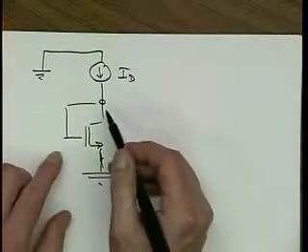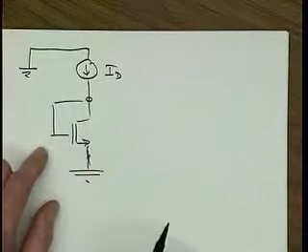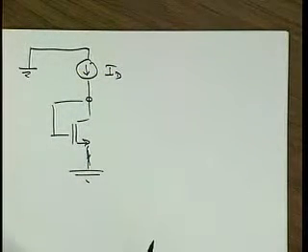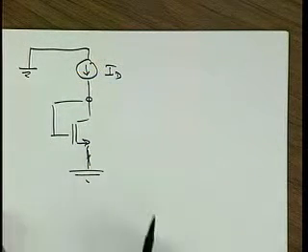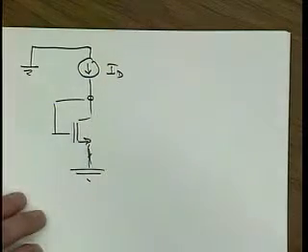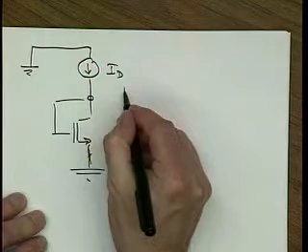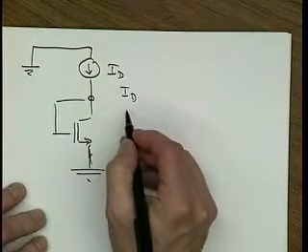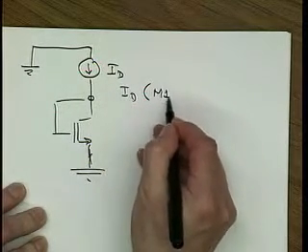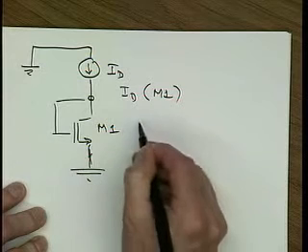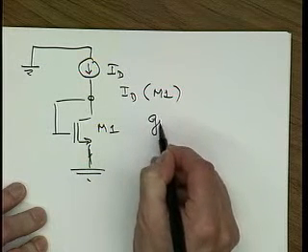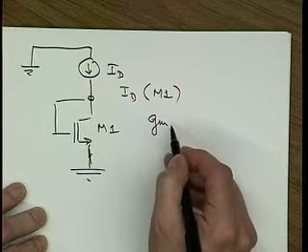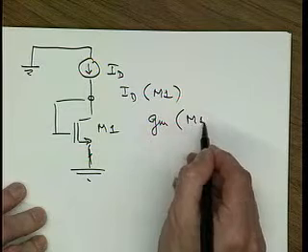Okay, so every version of SPICE has its own way to figure out parameters, right? It's straightforward to get out ID of a transistor, but just as you can get ID of M1, if this was called M1, you actually can ask SPICE also what is gm of M1 and so on.